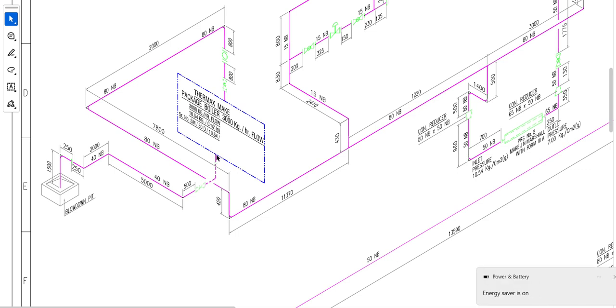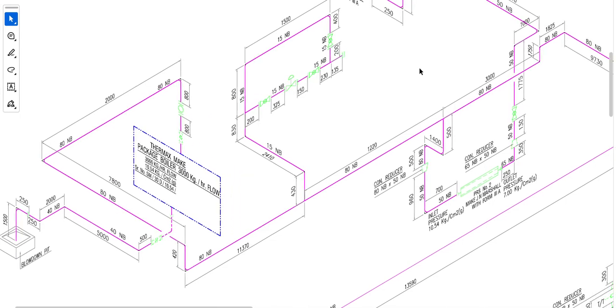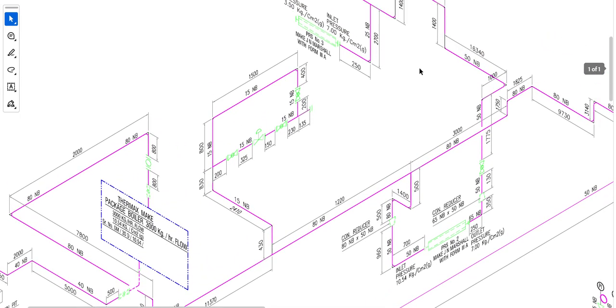And for the boiler, here we have the blow down line, and that blow down line goes to the blow down pit. From here our main steam line goes to the plants. Our main steam line goes to the plants via various pressure reducing stations. We have the first pressure reducing station here, so it looks like this.